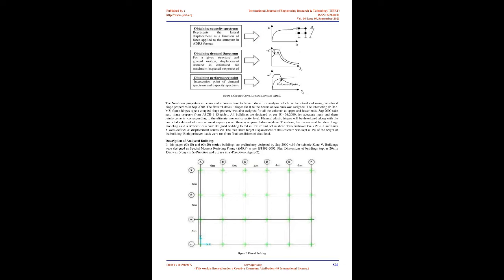The current seismic design codes in India and most of the other countries follow the force-based design, FBD, method. The force-based approach does not give an idea about how a building will perform under seismic loading, whereas the displacement-based approach, also known as performance-based seismic design, PBSD, evaluates how the building is going to perform under a given seismic loading.